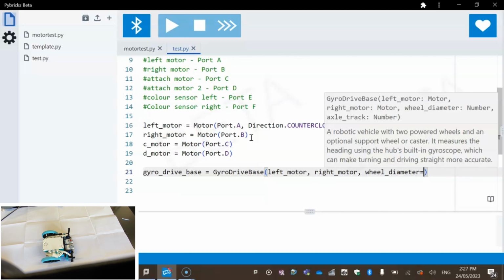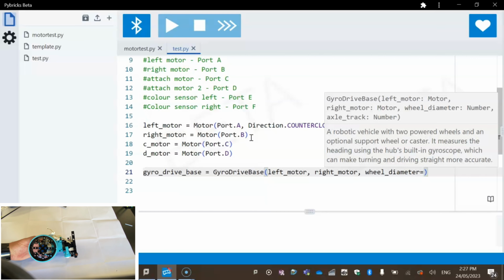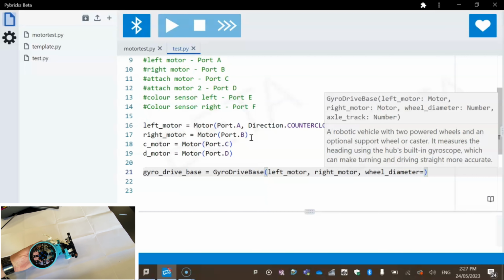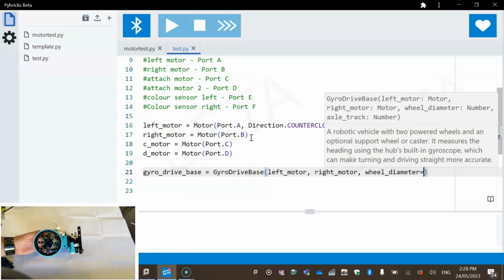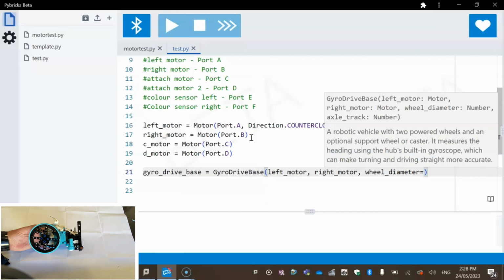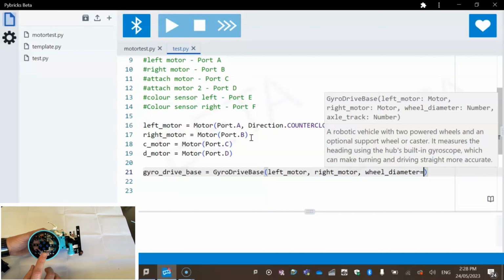Something that I'm using, and you'll notice a bit different here to some normal robots, I'm actually using the giant wheels. And the benefit of Pybricks over some of the other platforms, particularly Scratch, is that these big wheels typically cause a lot of error. They cause robots to be driving all over the shop, and they're really difficult to maintain a very tidy heading at the best of times, especially with turning. But with Pybricks, we've found that they are 100% reliable, and the added speed that we get from having bigger wheels is a big difference, and we'll see that in a second.